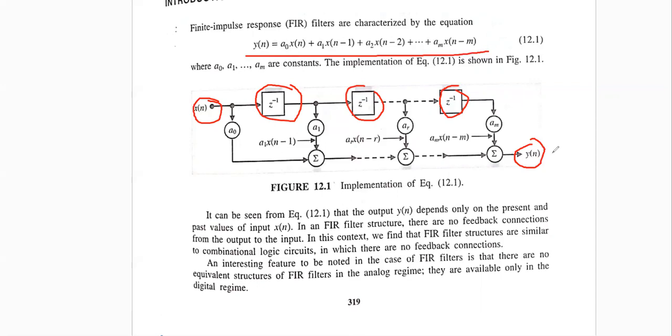The fundamental difference between the FIR and IIR system is that in case of FIR system, we don't have any feedback from the output to the input or anywhere. For the IIR filter, there is some feedback, and we are also introducing some delay. There might be one delay, two delay, three delay, any sort of delay. So the FIR filter only needs your input and the delayed version of the inputs, and that is all we need.